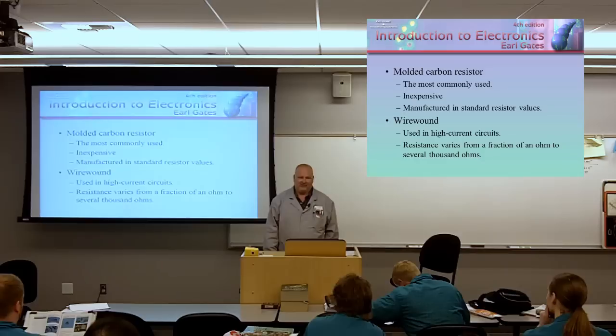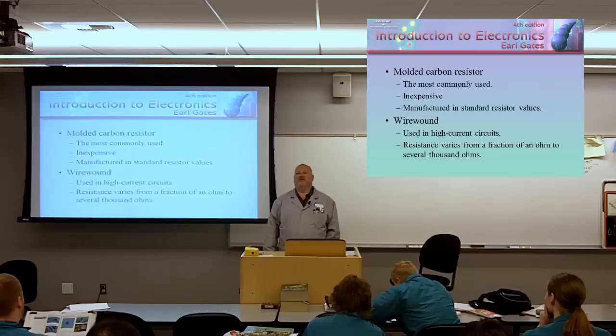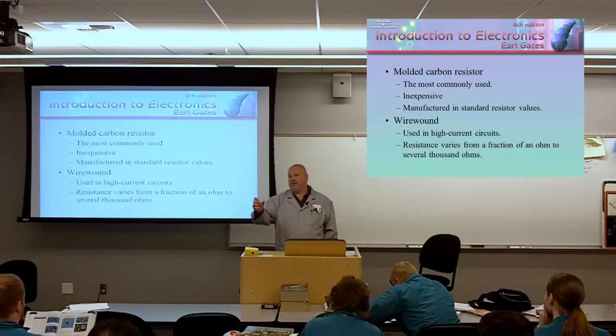Don't expect to find that on the market. You could go buy a package of 100 ohm resistors that are plus or minus 10% and start going through to see if you could find one that's 103.5. But an engineer is never going to specify, I want a 103.5 ohm resistor in the circuit. They'll say, I want a 100 ohm resistor. Standard sizes.